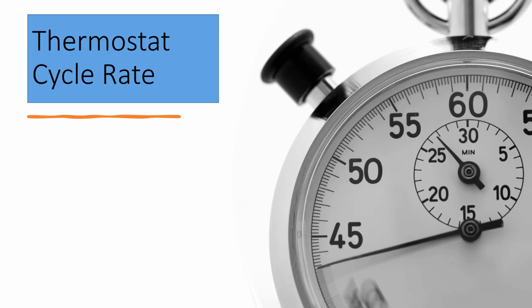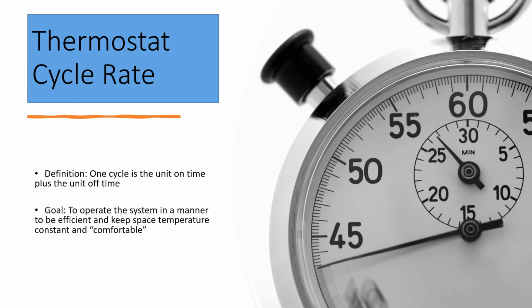First, we need to define what a cycle is. A cycle is defined as the unit off time plus the unit on time. Why is the cycle important to us? If we set the cycle rate properly to match the equipment, the system will operate in a manner that will keep the space temperature constant and comfortable for the occupants and help efficient equipment operation.